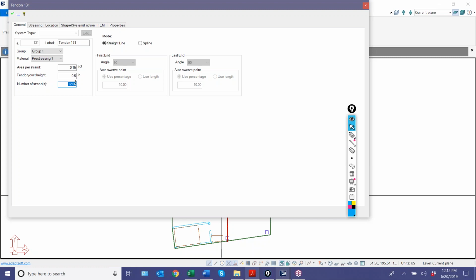There's different ways to model that. You can model one cable that equals 1 strand and do 12 of those. So that's taking it to the extreme. The more broken out the number of cables you have, the better control, or let's say the more accurate the deflection in the program. So if you're trying to get the most accurate result for deflection, and it's very, very sensitive, you might actually take banded cables and break them out individually versus representing them as a lump value of strands like so.